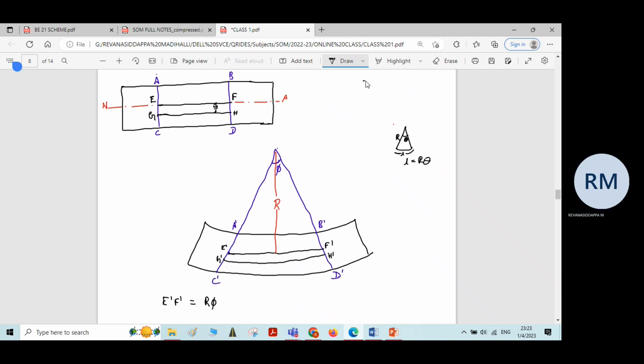You might have studied the stress strain distribution of the beam. So at bottommost layer we will get the tensile stresses, and at topmost layer of the beam you will get compressive stresses, and at some particular point on the beam there will not be any compressive stress or the tensile stress.